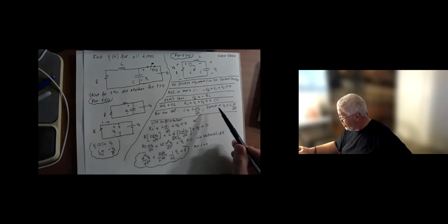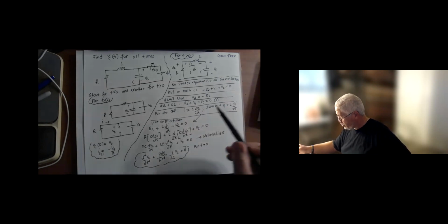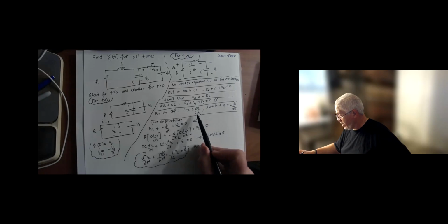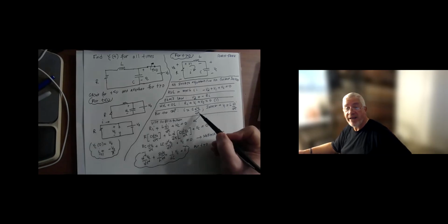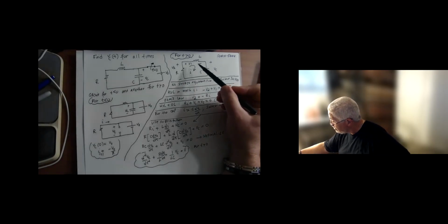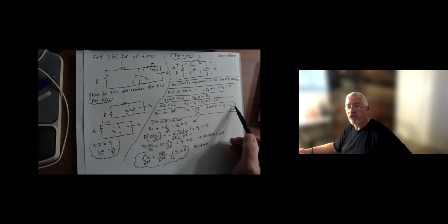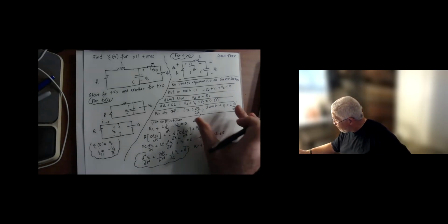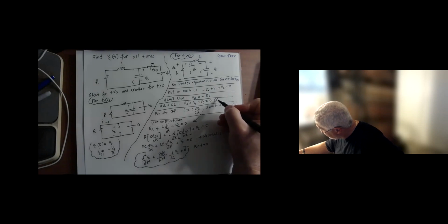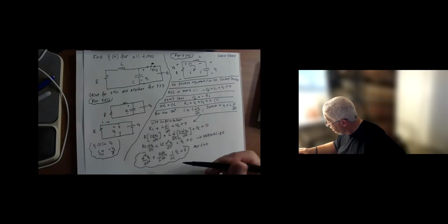And then I write the capacitor and the inductor relationship based on what I have in my circuit. Of course, this looks a little bit like a generic equation, but it's not. The current to the capacitor is I, and the capacitor voltage is VC. I make sure that I satisfy the passive sign convention when I write this relationship. Is the current entering the positive? Yes, it is. And then for the inductor, the voltage is equal to the derivative of the current multiplied by the inductance. Then I bring them in, so I have these two equations and the KVL equation. So I have 3 equations, 3 unknowns, and I'm going to basically use substitution to get down to 1 differential equation.